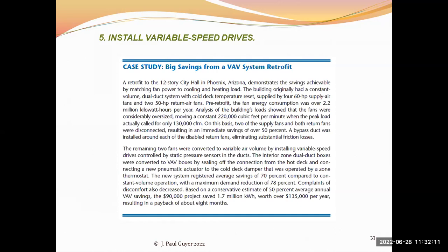The remaining 2 fans in this example were converted to VAV by installing variable speed drives controlled by static pressure sensors in the ducts.